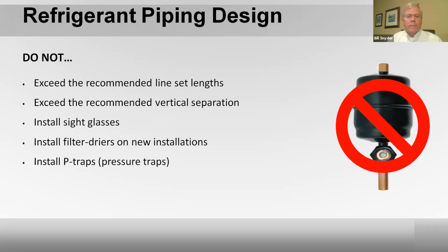take a filter and, say in the air conditioning mode, put it in what would look like a liquid and a suction line. As long as you knew the direction of the flow of the refrigerant, put it in there and try to clean the system up for, you know, an hour, and then change it again, and then let it run for maybe a week, and then change it again, and then actually remove it. I would not recommend leaving a filter dryer in our system.